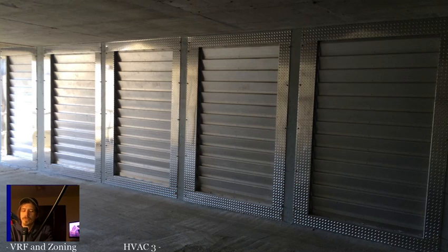So if you do a lot of chiller work, you want to read up a lot on centrifugal chillers to make sure you understand things like purge units and inlet slide valves, inlet guide vanes, which are going to redirect the refrigerant to control capacity and things like that.